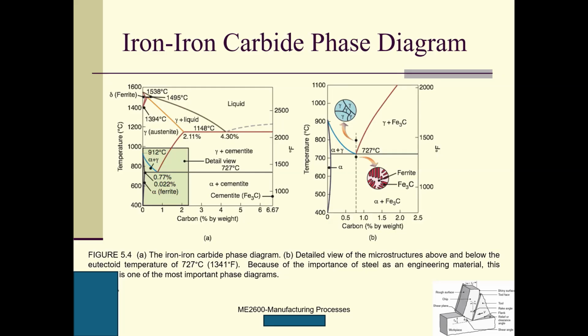Right? So here, this is different carbon content, and you can see this is liquid, this is the liquidus. So this is gamma. Gamma is austenite. These are different phases. This austenite is called gamma. This is a pure gamma, solid. However, this area is gamma plus liquid. So here is alpha plus gamma.